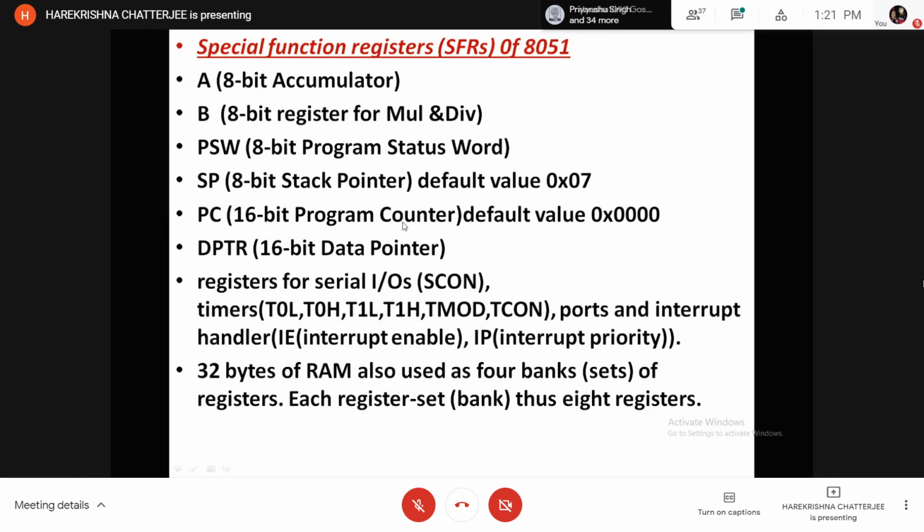But programs are burned in program memory, while we implement the stack in the read-write memory. The stack is implemented by the programmer by initializing the stack pointer, but it is implemented in read-write memory so that data can be stored in it and retrieved from it without using the ROM burning mechanism. So the stack should be implemented in the 128-byte data RAM.